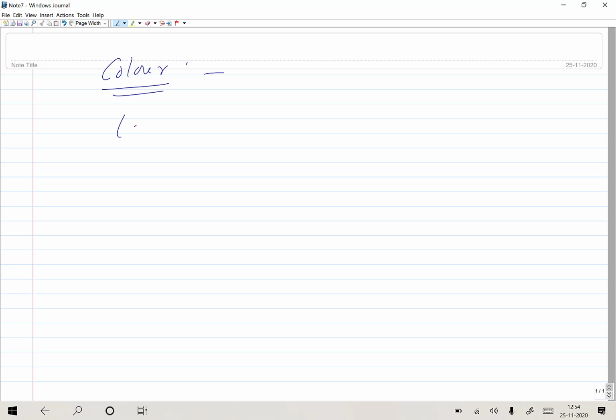Then label coding. Label is like writing the details. Like this is for the speed regulator, this is the feed regulator, or this is for the water supply, this is for the oil supply, like that. So you write the details in text. So that is label coding. Okay, so these are 4-5 types of coding methods. As I said, size, shape, texture, location, color and label coding.